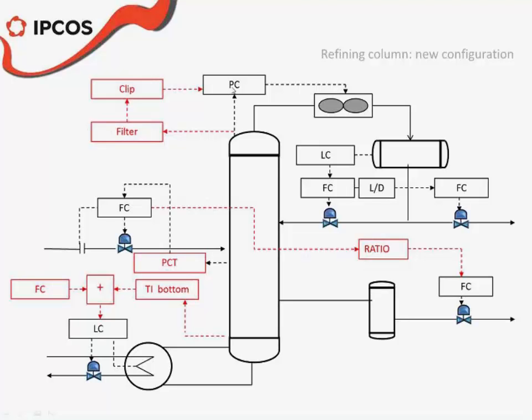This at the end keeps the pressure floating but not changing drastically like it used to do before. Before, because the set point was constant, the fin fan coolers were pretty much just opening and closing all the time, and no real regulation was done.